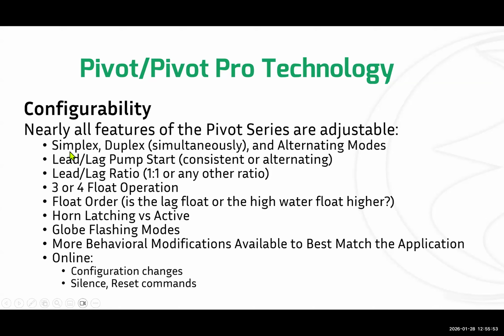But here are just some of the things that you can do. If you have a duplex panel, a two pump panel, you can set that to simplex mode if for some reason you don't want to use two pumps. You can quickly and easily do that. When we say duplex, what that means to us is true duplex, meaning if the water level rises high enough, it will call both of those pumps to run simultaneously. So it'll run both pump one and two at the same time.